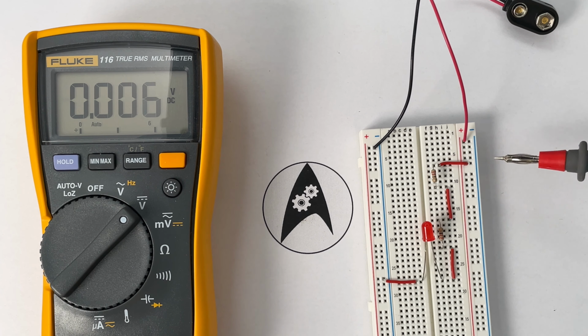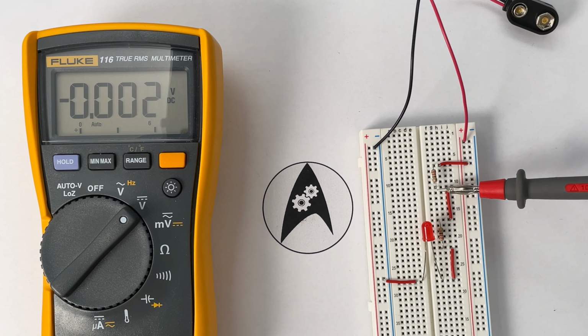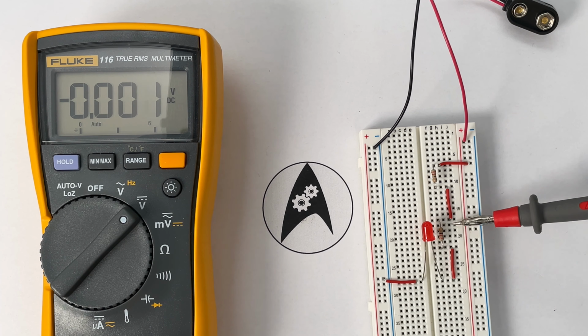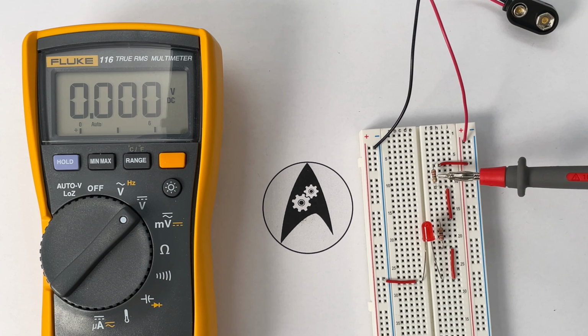And now let's take a look at the circuit as it's designed here on this breadboard. If we follow the path of the current, the technical current direction, the current enters the breadboard here in the power rail, flows down to this jumper cable here, is directed into row number 7. From there, it takes its path through this resistor here, and from the resistor, once the electrons leave the resistor, they flow into the other jumper cable in the middle here, down to the second resistor, which has the same color code as the first one. So basically, the two are the same, plus minus a few percent for tolerance.